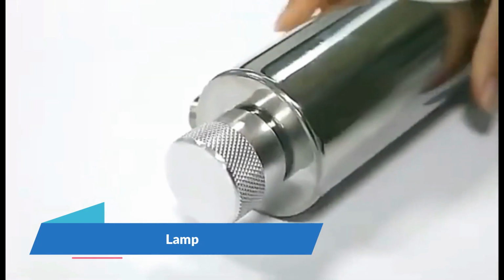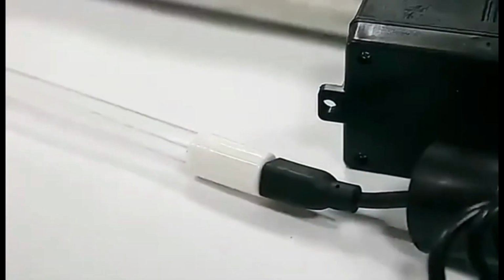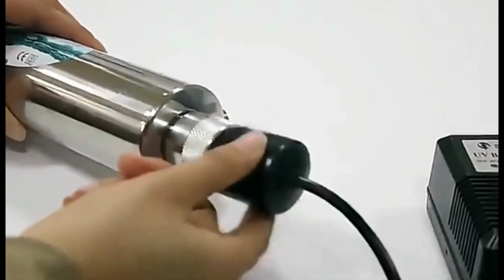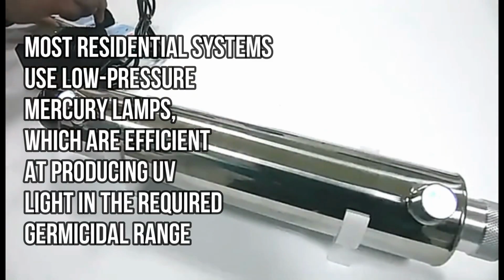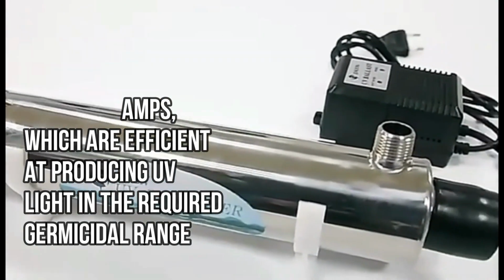1. UV lamp. Function. The UV lamp is the core of the purification system, emitting UV light at the germicidal wavelength of approximately 254 nanometers. Types. Most residential systems use low-pressure mercury lamps, which are efficient at producing UV light in the required germicidal range.